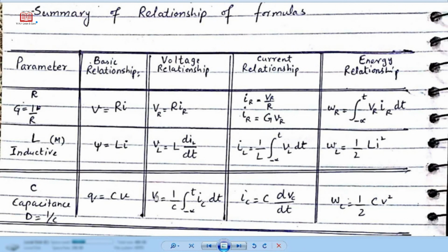Like here, if we are going to calculate the voltage, you are not going to replace the voltage with the current, as in this case. So voltage is again voltage, because you are finding the voltage for the capacitive circuit, so voltage is not changing. Here it is L, now it is replaced with capacitance and inverse, 1 over C. Here derivation, now integration, here I also dt.